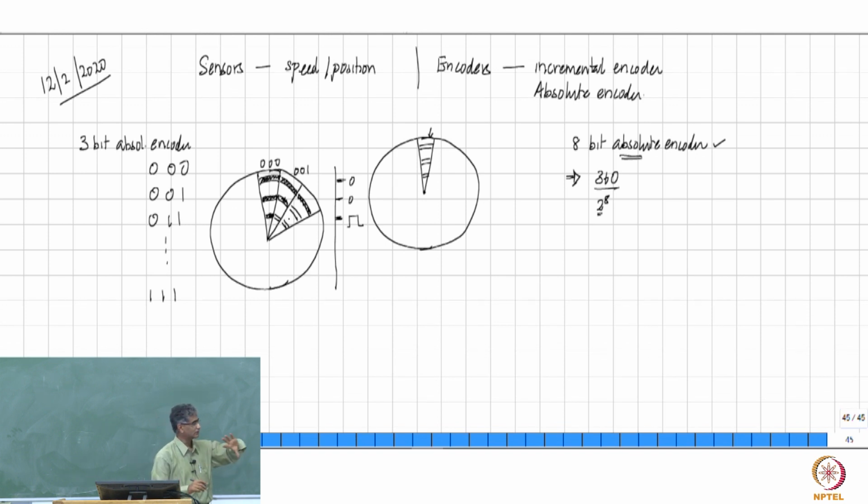So if the disk is now going to rotate to this angular disk position, then you would have an output as 0, 1, 1. So accordingly, as the disk moves, you will get different varieties of outputs, and depending on what you detect, you can immediately know at which angle you are, and therefore this can be used as a measure of absolute angle. But then the difficulty is you can't really afford to go in this order.